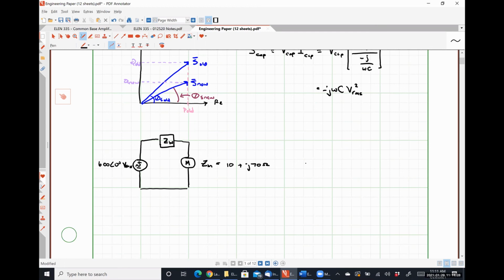And for the sake of argument here, let's say that my wire has an impedance of 0.1 ohms plus j0.05 ohms. So we should see that for any real transmission line, it's going to have some real resistance, representing the resistance of the copper over that long section of wire.